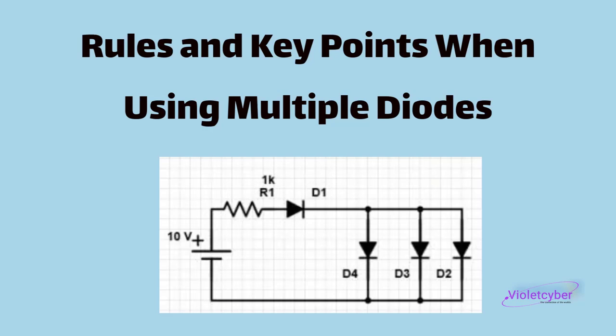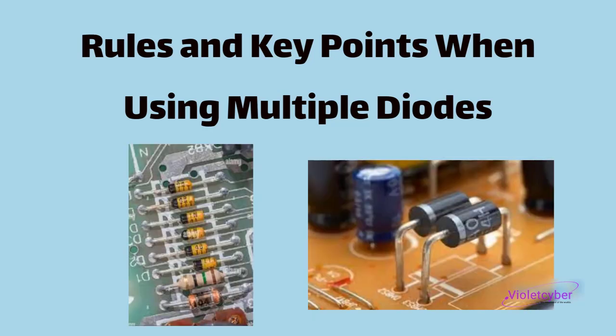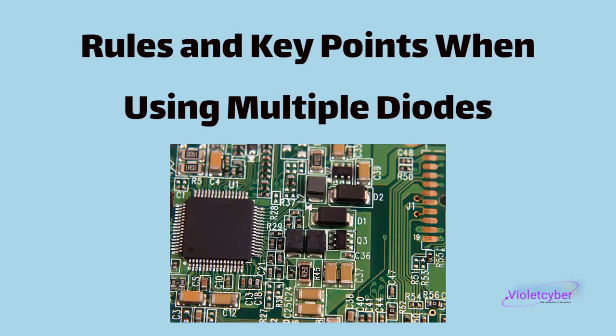Diodes must handle the required current and voltage. In any diode combination, ensure the diodes can handle the required current and voltage. Attention to total voltage drop in series connections. In series connections, the total forward voltage drop increases, which may require a higher voltage to drive the current. Heat management. In circuits where a large amount of current passes through the diodes, heat generation is a concern, and using cooling systems or heat sinks is important.